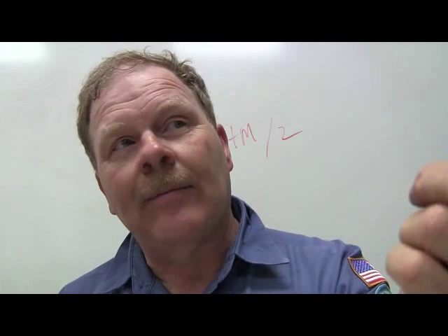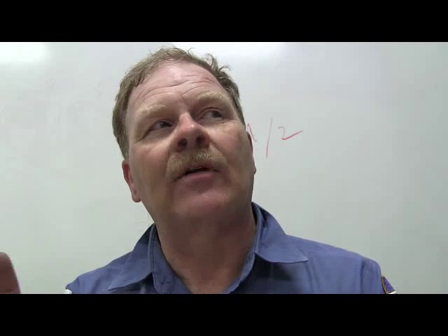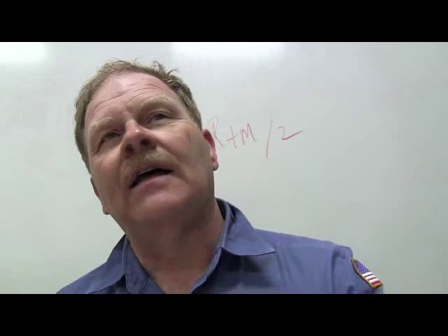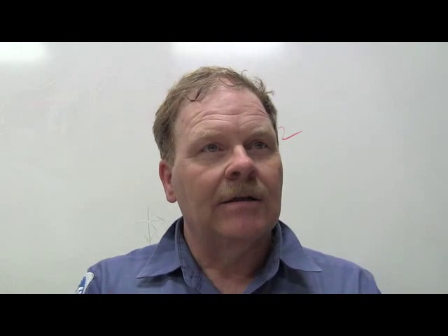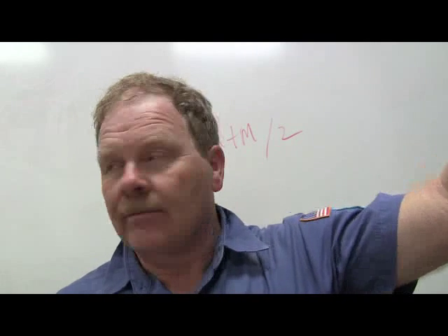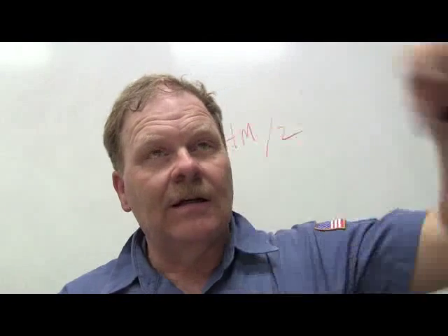Right before it goes into the evaporator, though, it's going to turn into an atomized low pressure liquid, so it can evaporate in the evaporator and absorb heat. And then it's still absorbing heat all the way out of the evaporator to the compressor. If one's fully charged like it's supposed to be, that suction line is going to be cold all the way to the compressor. If the accumulator is cold on these orifice systems, that's okay, but that line needs to be cold. And sometimes they get so cold they get frost on them. You ever see them do that?